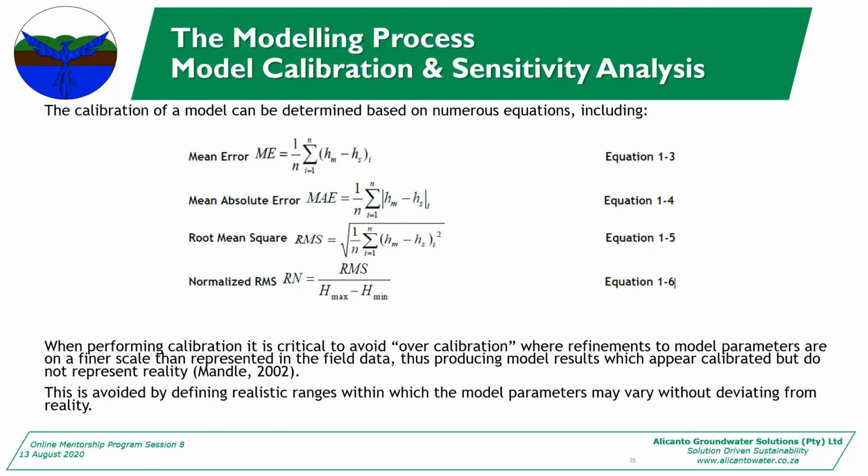No, I agree with that. And just one last comment. Sorry for talking so much. Somebody mentioned earlier something with regards to how you structure your fieldwork, your numerical model and the calibration. Your conceptual model will add to how you structure your fieldwork because you will know which data gaps to close. You cannot go out to the field with an uncalibrated model, but if you have a conceptual understanding of your approach and what you need to input into your numerical model to calibrate it, then that will structure your fieldwork.